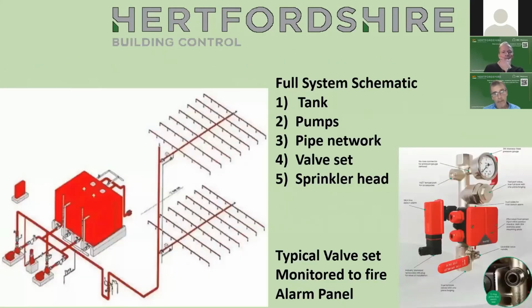If we went back to that, if the maximum situation is 4 heads going off, you would work out the internal friction of that pipe, that bend, all of that gubbins around there back to the tank. And then the static head, and that would more or less dictate the pump, because if any of these 4 go off, it won't require as much pressure as those 4 going off. So worst case scenario, you're working on 4 heads going off.